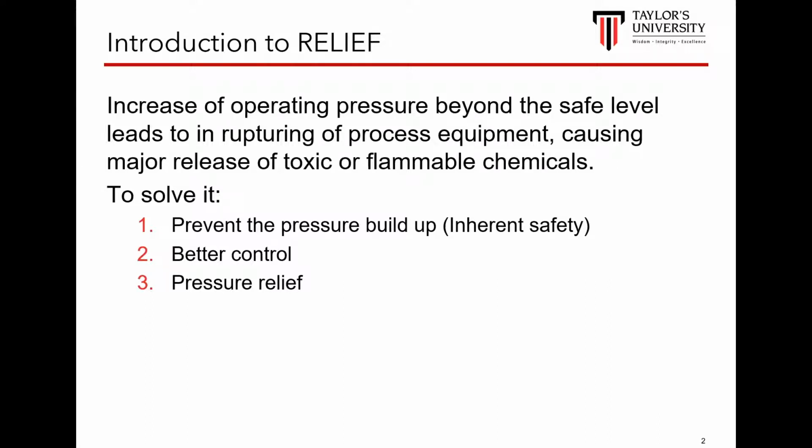So to resolve this, we first want inherent safety, which is the first line of defense to prevent the pressure buildup. A second line of defense is to have better control of the process. And of course, the third line of defense is where we install a pressure relief system.